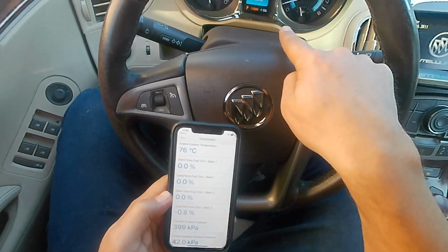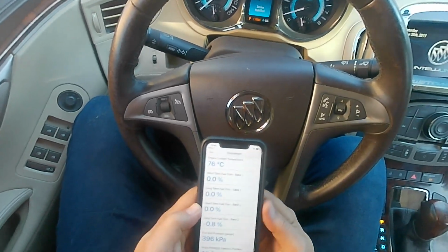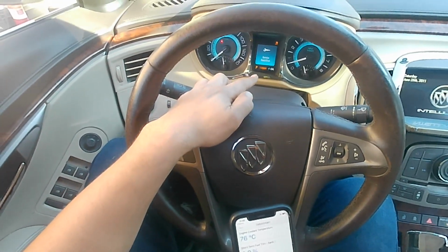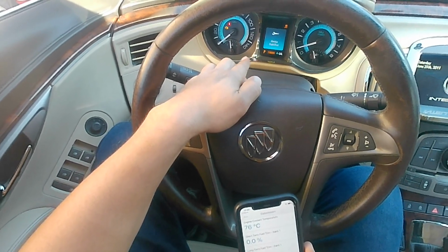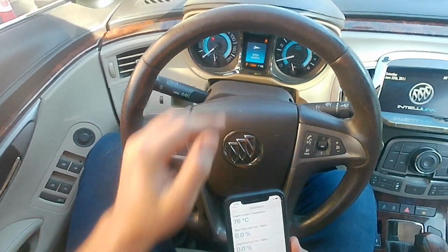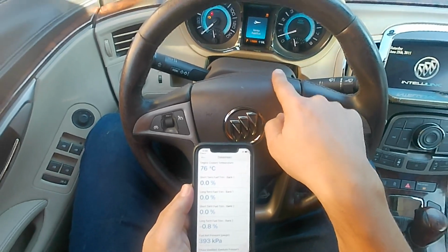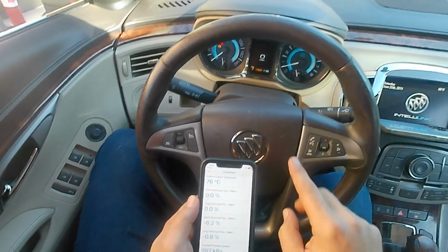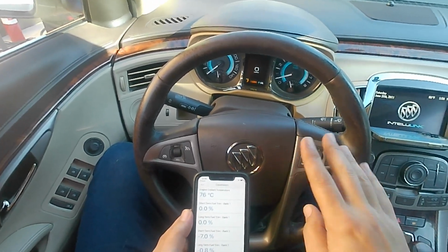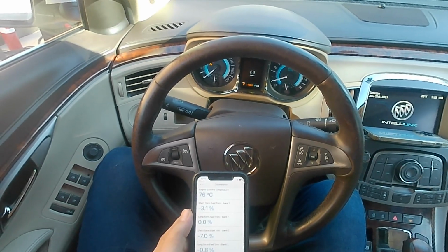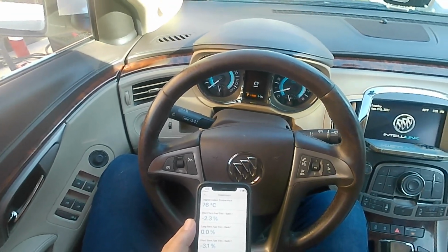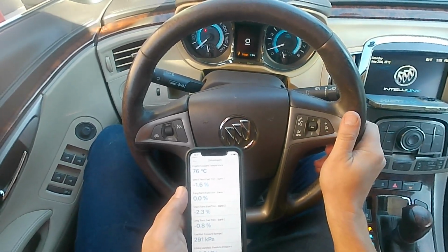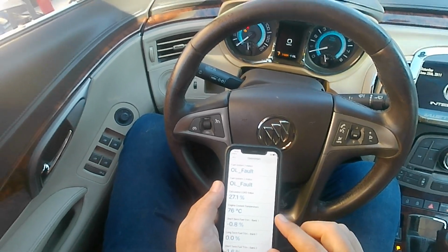Now this is the error message that we are getting along with the flashing check engine light. I hope you guys can see it. So, service StabiliTrak control, and this message is actually associated with a flashing check engine light and with misfires or any other components, faulty sensors on the vehicle. And I can feel the vehicle is shaking, and idle is running rough.